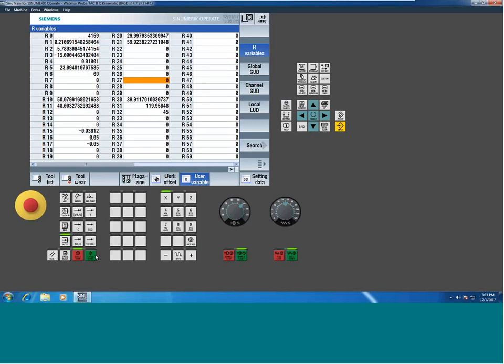and take our first measurement, and there we go. So it just came up. So in this case, based on where things fell and where it wants to trigger that switch, it thinks that I'm 200 thou past 0. Now I come over and I go grab the measurement on the other side of the block. So she moves over, takes my measurement. I think I went one more cycle stop in there. Oh, so I came over, took that measurement, and then we did a little bit of math, figuring out what that center position would be. And then I just drove that value in there.